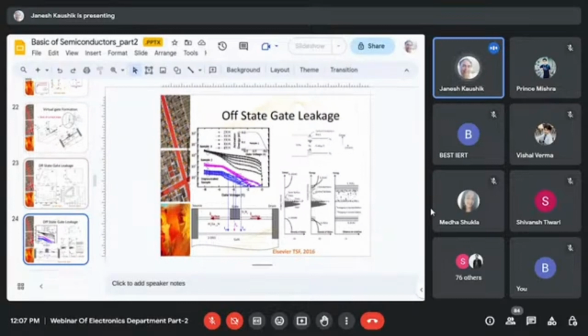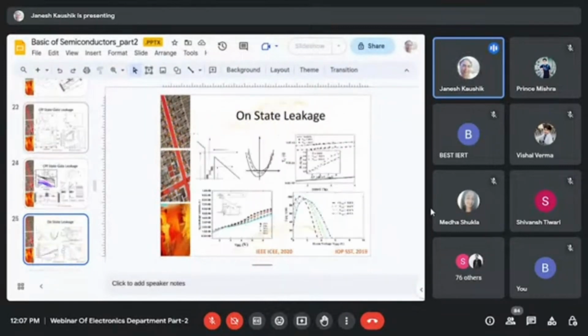I mean, the gate leakage current is also present, and the model completely explains how this higher gate leakage is taking place with the smaller drain current collapse in these devices in this particular case. But if you see, the off-state leakage is when the transistor is off, meaning it's reverse biased to the point when the 2DEG channel is not present under the gate, but gate current, leakage current, is present when we operate the device in normal transistor operation.